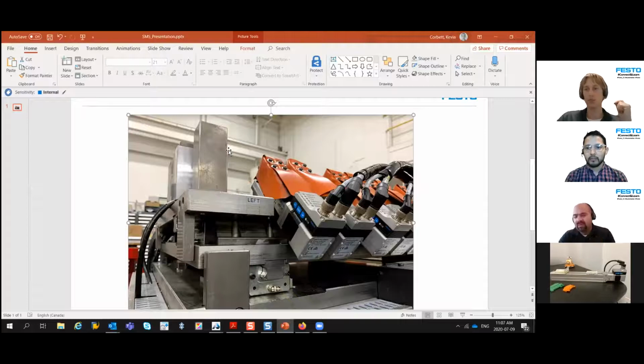But if it's super long and you're out of the range of a standard sensor, then you would need to change to a larger sensor. That's one of the constraints with position transmitters: there are only several lengths, and that's it. If you have a longer actuator, then you're screwed, because there's not going to be a solution unless you use two or something. But then it gets a little bit more complex.